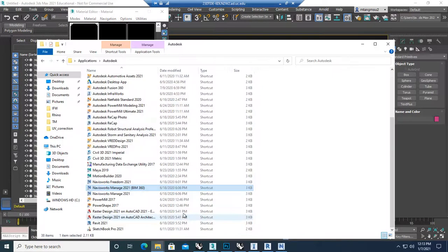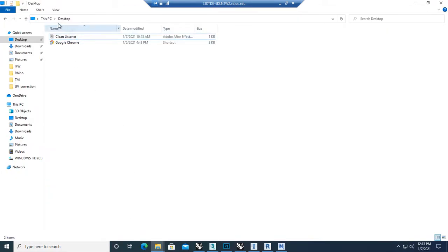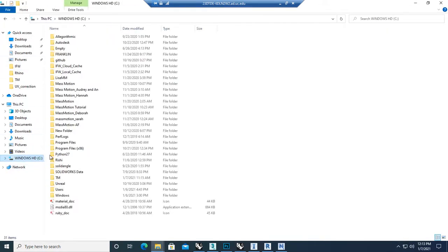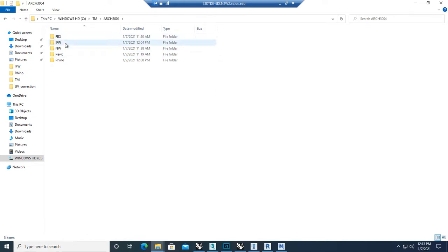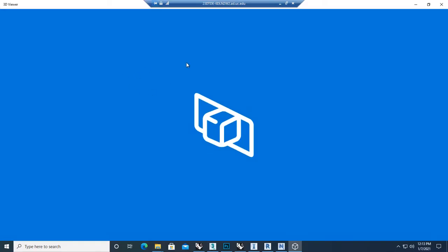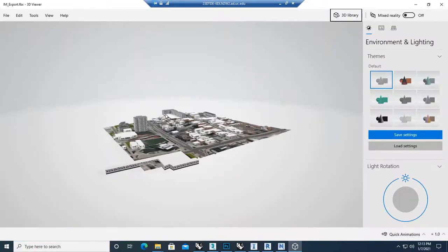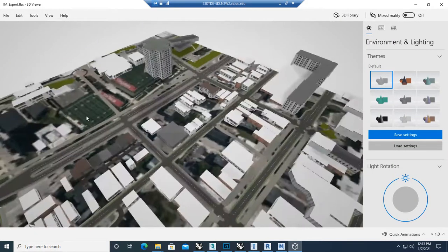However, if you double click open the same file in some basic program like Rhino or 3D viewer, the texture looks wrong. Right? So if I go to here, go to the Infraworks model, if I double click right here, this is open in the 3D viewer, really basic program. This program doesn't understand what the -1 means for UV mapping.